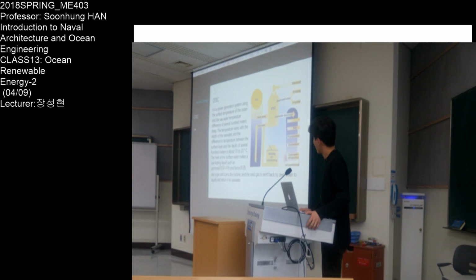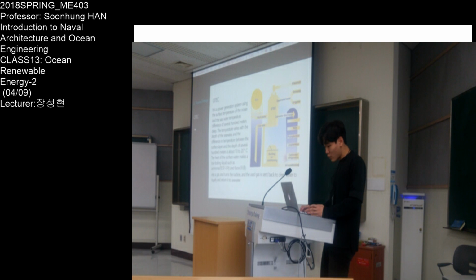Next one is ocean thermal energy conversion. It is a bit different from other thermal energy. It has a very low temperature difference, and it uses low boiling liquids such as ammonia and freon turned into a gas, which goes to the turbine, and the used gas is sent back to deep water.